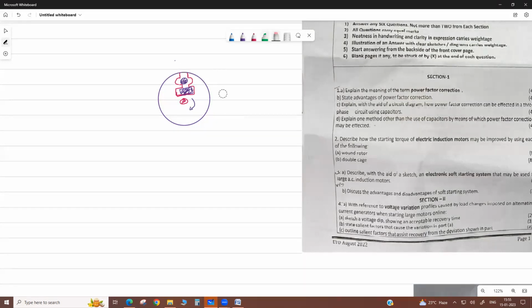No, not in first rotate. First, there is a flux in the air gap. The resultant flux links with this. Now these rotors are short circuited, so current flows. There is a current in the inner cage and outer cage. There is current in both conductors. So actually there are two circuits in the rotor. In the rotor equivalent circuit, there is rotor resistance and reactance.